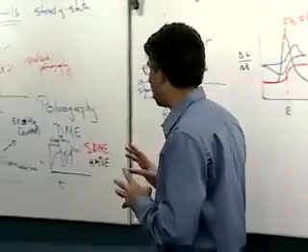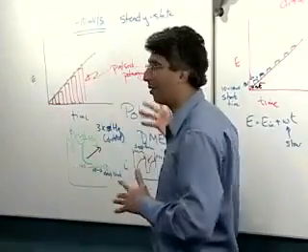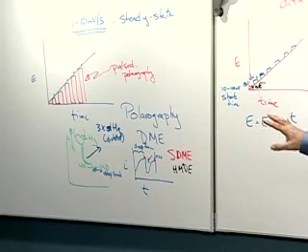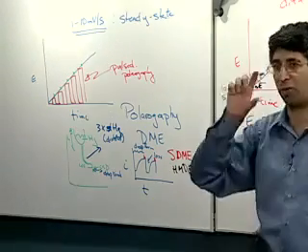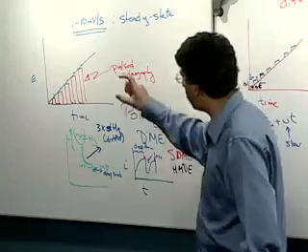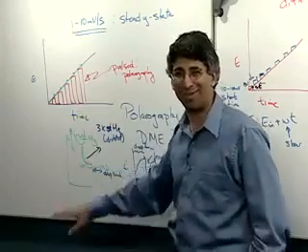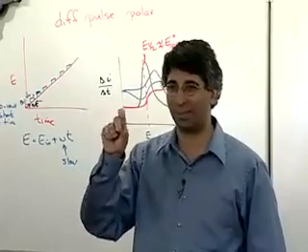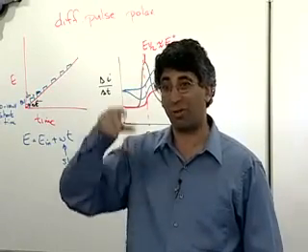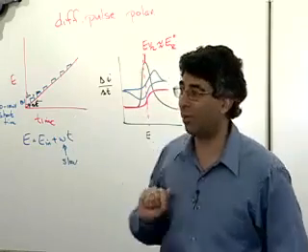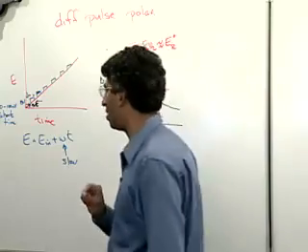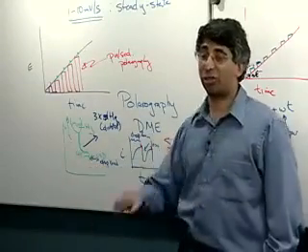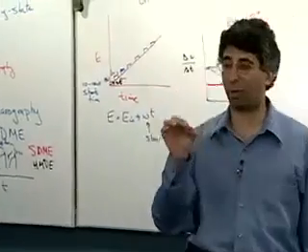Number two is, today, really it's only come out in the last 20 years or so, there is a more sophisticated way of generating these mercury drops. What's done is you can buy a system which pressurizes the mercury reservoir. So there's no more of this lifting or drop knocking business, but it pressurizes it with a little relay piston system that generates a pulse. And so you can pressurize mercury through the system, and you can very precisely regulate that, both in terms of the time of the drop and in terms of the size of the mercury bead that you generate.